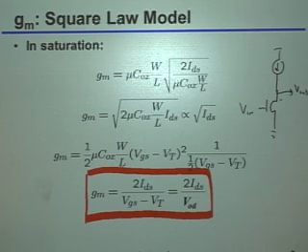That VDSAT would basically say, what's the minimum drain to source voltage you can apply across that transistor, and make sure it basically stays in the quote-unquote high gain region, in the saturated region. And so indeed, the smaller you make that VDSAT, the closer you could shove the output to ground, and therefore the larger swing you would get, right?